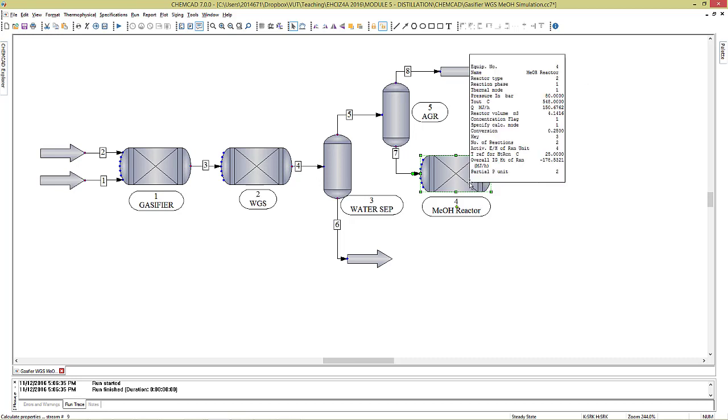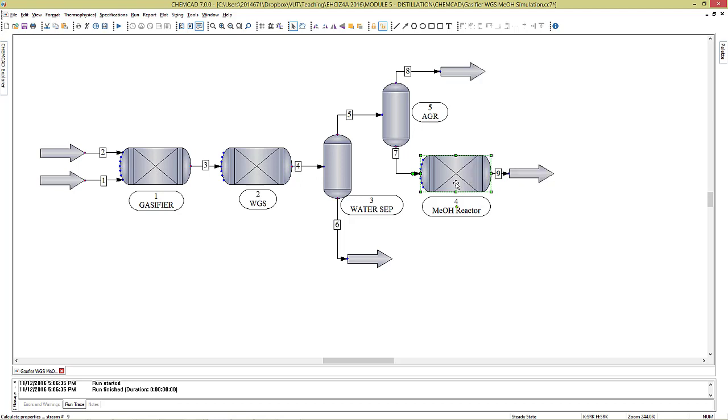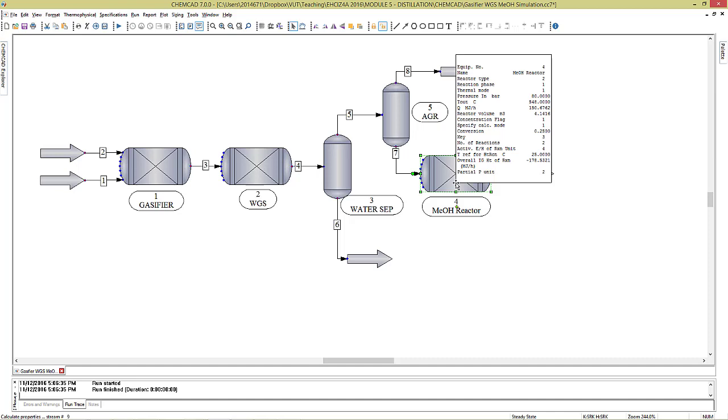You can see how far you can push the conversion of methanol while still getting the reactor size that makes sense. Here our reactor size is 4 cubic meters. I still think it's a reasonable reactor size. Then you can try and push the conversion to 30%, 40%, 50% and see how big your reactor gets. If the reactor gets unnecessarily big, just look at the dimensions of how the reactor is going to be. If you look at the diameter and the length to make that volume, sometimes you end up with a very large reactor. Students submit a reactor that